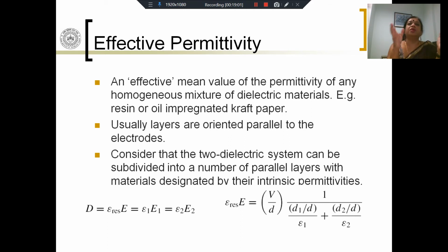When we are building bushings, epoxy resin is a polymer which is very commonly used for the creation of bushings. Before using it in the bushing, we incorporate micro-sized metal oxide particles. The result is that the structural integrity of the epoxy increases. So you have a composite material which is no longer homogeneous, and you have two different materials uniformly distributed.